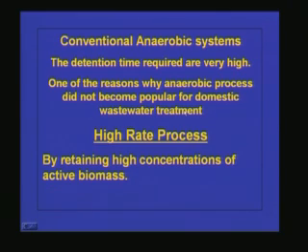Though anaerobic treatment was the first to come into existence in 1935 as a treatment process, afterwards the aerobic system took over, because in an aerobic system we can achieve very high efficiency, say 90 to 95%, within a few hours. Usually we give 8 to 10 hours HRT in the aeration tank. So compared to this, the anaerobic system requires a lot more time, and naturally the volume of the treatment system will be very high.